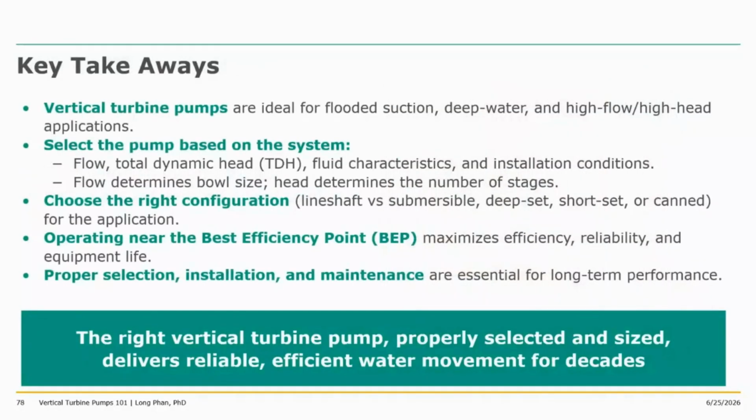So the key takeaway for today's webinar. I hope you stayed awake during this afternoon time, but we finally arrived at the last slide here. Just a little bit of summary for you all. Vertical turbine pumps are very ideal for flooded suction, deep water, high flow, high head, even low flow, low head too. They have a variety. Their envelope, as I showed, can adapt to any design conditions.